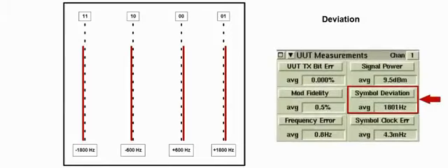By the same token, a zero-crossing frequency error meter relies on equal distribution of the deviation points. The distribution points of the C4FM signal are rarely equally distributed, so the zero-crossing frequency error meter will also produce misleading results. The frequency error of the carrier shifts the deviation of data points globally in the same direction. However, each data point will have its own amount of deviation error as well. The symbol deviation meter is used to provide a measurement of the average deviation of the data points.